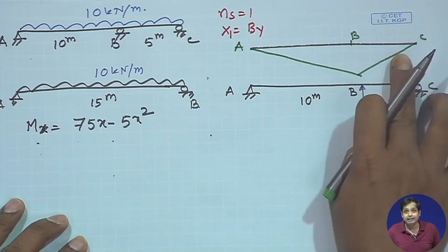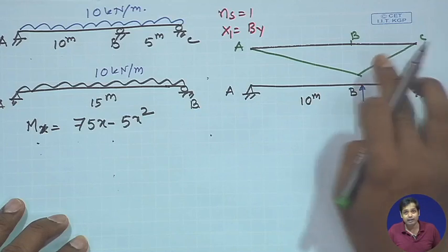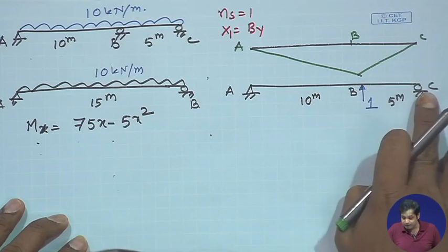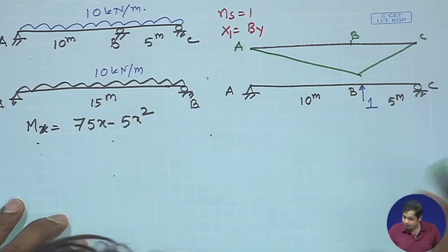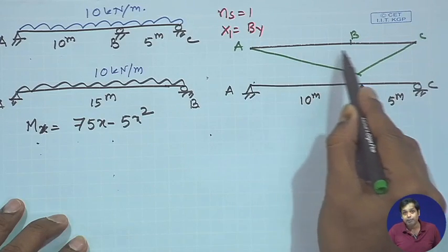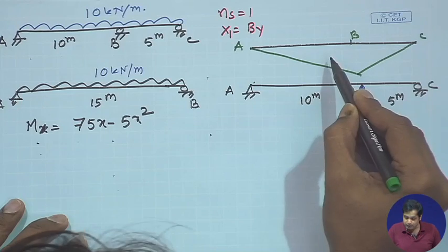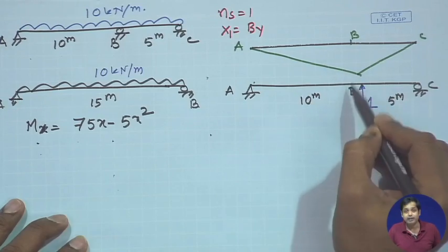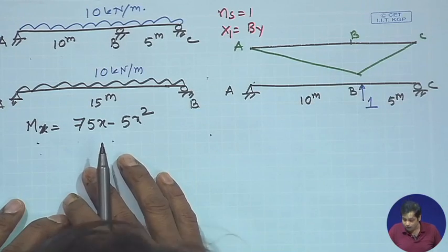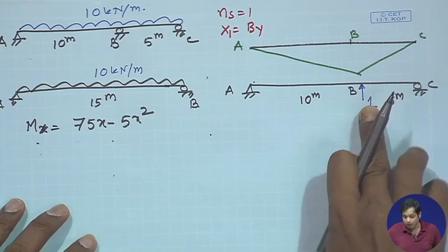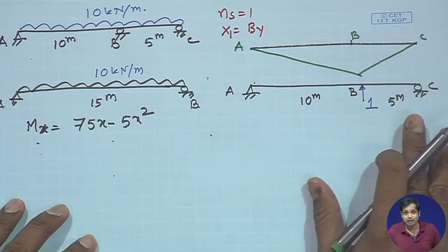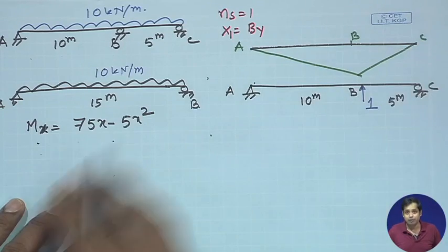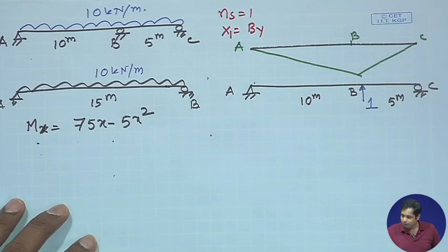The bending moment is shown here downward, because in this case the load is acting upward, and therefore the deflected shape of the beam will be like this. The bending moment that will be generated is a hogging bending moment, because this load will cause hogging in this beam. Hogging bending moment is negative as per our sign convention, that is why it is drawn like this. Now, what is small m?